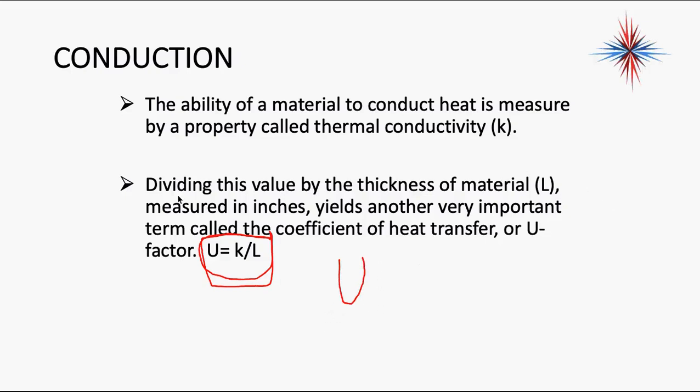I'm not going to have you find the K factor. You probably won't use that at all. I'll give you tables for that, but we use the U factor. It's the coefficient of heat transfer. Again, you won't have to calculate that because I'll give you tables that do that, but you have to understand what it is.